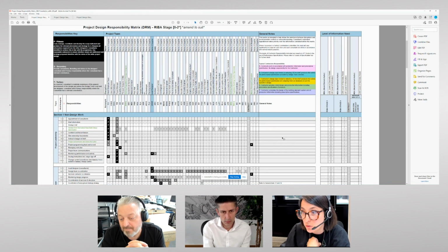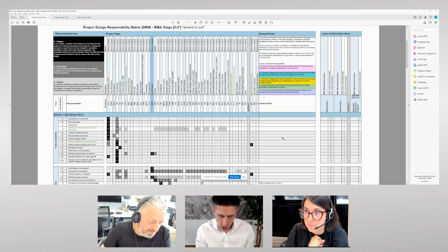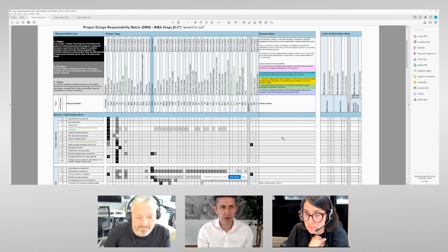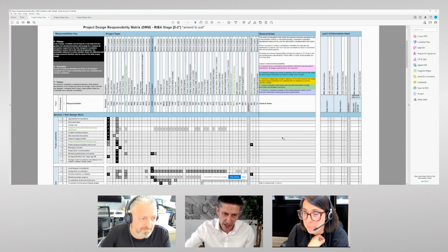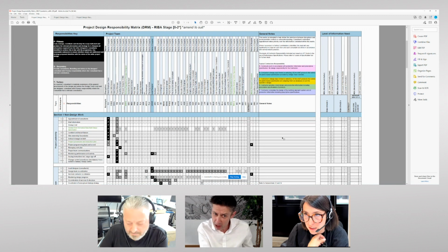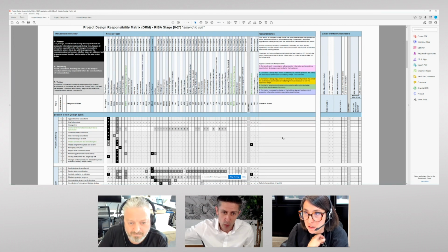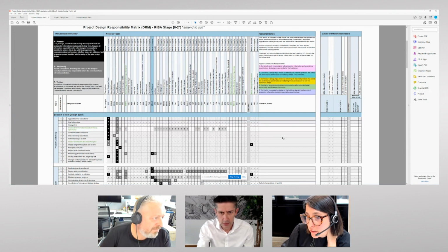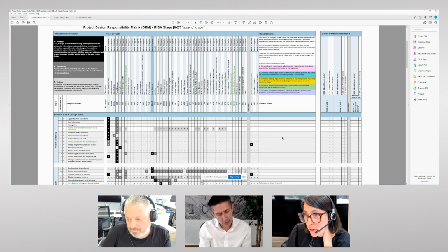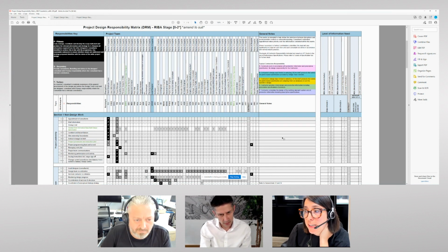So they're making sure that they're using the right one and they understand to what detail they need to write their specification. And when it's P for prescriptive, I guess you're taking full design responsibility down to the manufacturer product. It's this flooring with this underlay with these fasteners. Whereas descriptive could be it must have a warranty for 15 years and the following slip resistance. Exactly. It will provide all the performance data that the contractor needs to make an alternative selection should they wish.